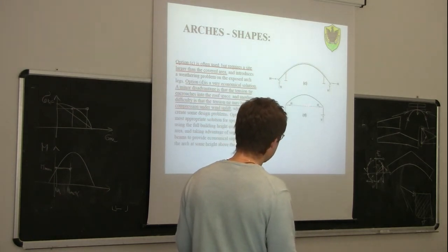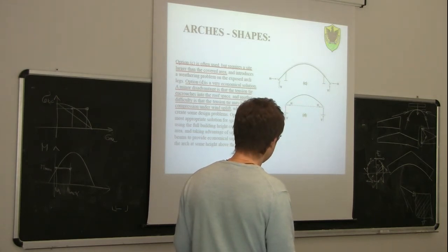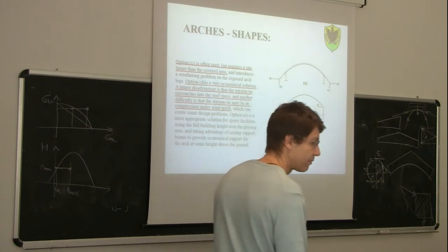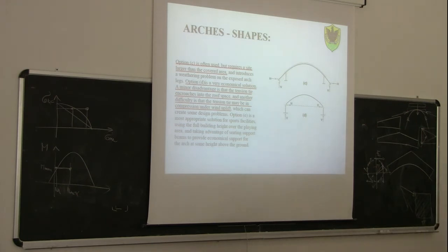This would be, from the structural point of view, a very effective solution. So we could put a tie rod here to connect those 2 points. So if we tie those 2 points together with a rod, of course, when we have a vertical load, this rod, by resisting in tension, will significantly reduce the flexibility and will keep the distance more or less constant.